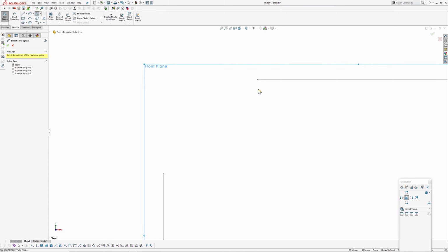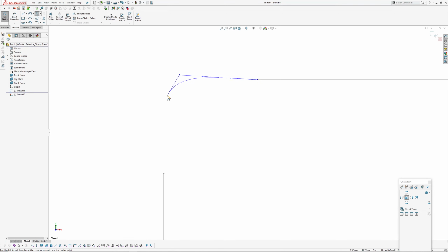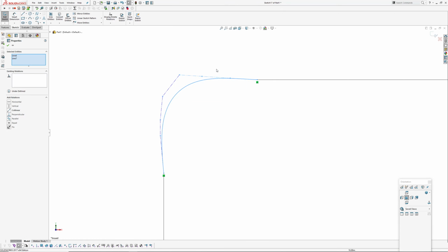So I'm going to show you how to make a G3 corner. So for G3, that means we need 4 points on the spline for each connection. So in total we need 8. So that means we need a degree 7 Bezier curve. So 1, 2, 3, 4. 1, 2, 3, 4. And pick those.